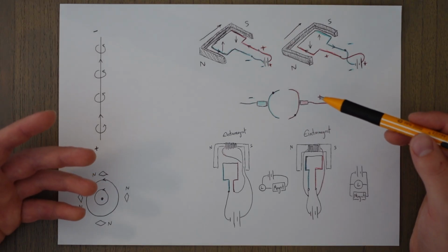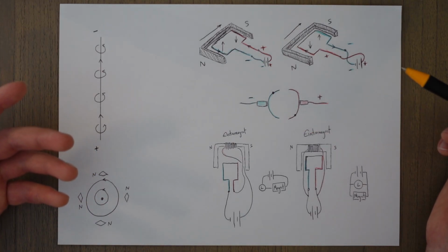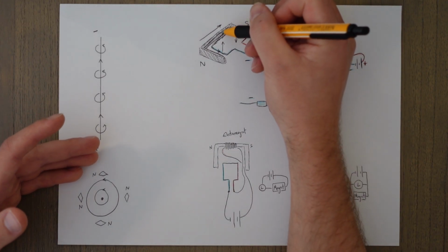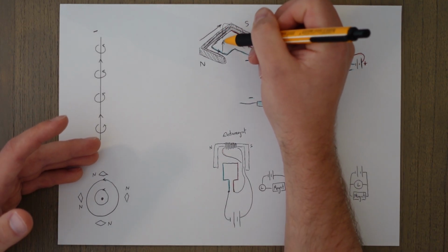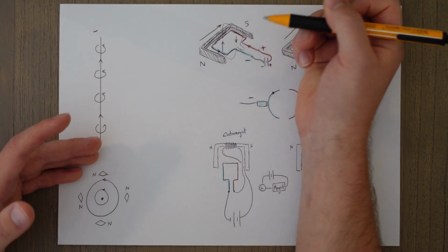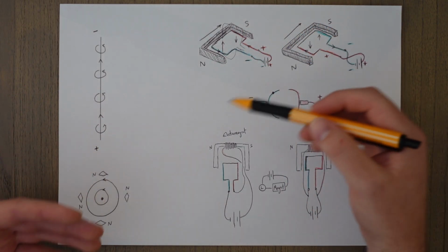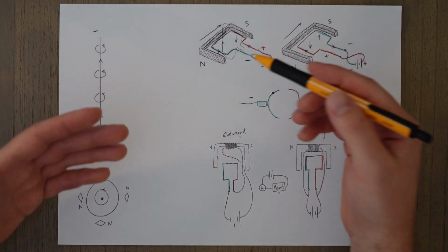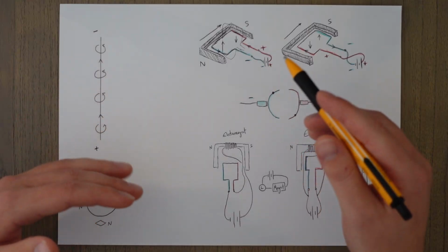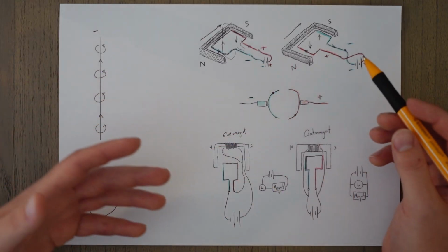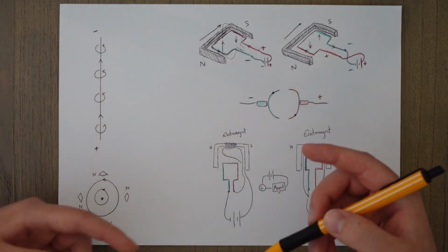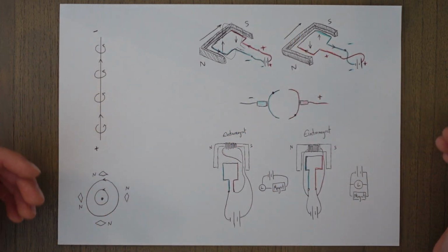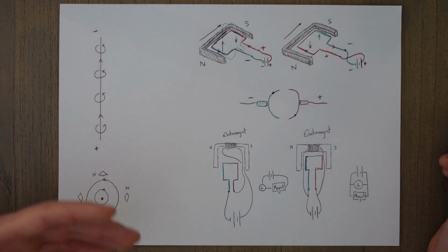To optimize our motor further, we can put in more loops of wire. If we put another loop of wire offset by 90 degrees, for example, and then enhance our commutator, we can have current flowing through both of those loops at the correct time. As the first loop reaches a dead zone, the other one is in the area where it feels the highest force, and that keeps the motor moving with a high torque level. And we can keep adding more and more loops to increase its efficiency as much as possible.